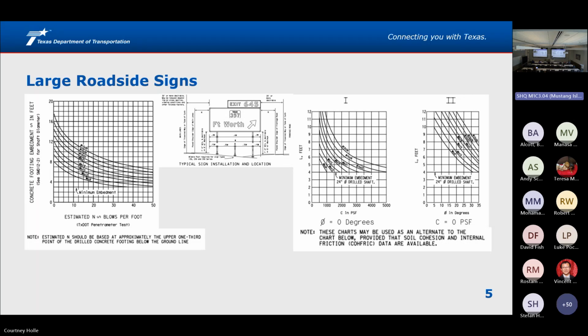One thing to consider here, when you're trying to determine what the soil strength is, is that these standards typically assume that your soil is uniform, which may or may not be true. A lot of the standards will indicate, here's the zone that we're looking at, here's the zone that we're concerned about. We'll talk about why that's important from a design standpoint when we talk about laterally loaded structures. But you have to pay fairly close attention to the notes on this one and some others to determine exactly what area we're concerned about when it comes to soil.